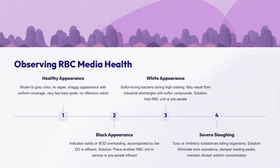Let's take a closer look at observing RBC media health. First, a healthy appearance typically shows a brown to gray color, with no algae present. The media should have a shaggy look with uniform coverage and very few bare spots. Importantly, there should be no offensive odors, indicating everything is functioning properly. Now, if you notice a black appearance, that's usually a sign of solids or BOD overload, which often leads to low dissolved oxygen in the effluent. To address this, the solution is to place another RBC unit in service or pre-aerate the influent to boost oxygen levels and reduce solids buildup.